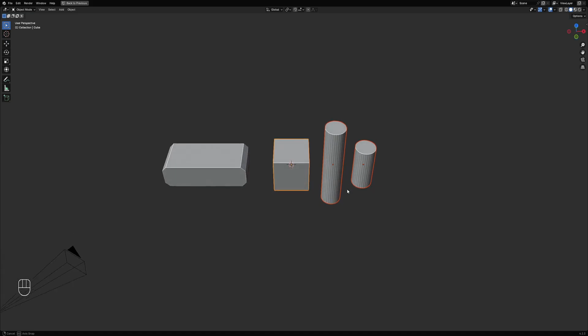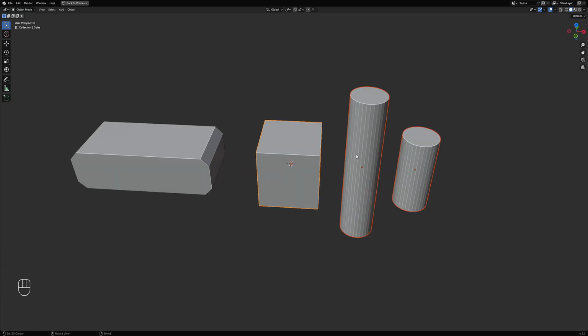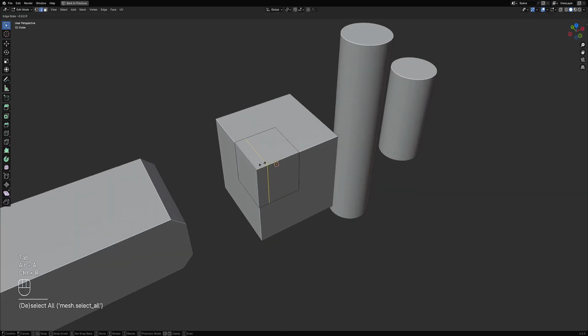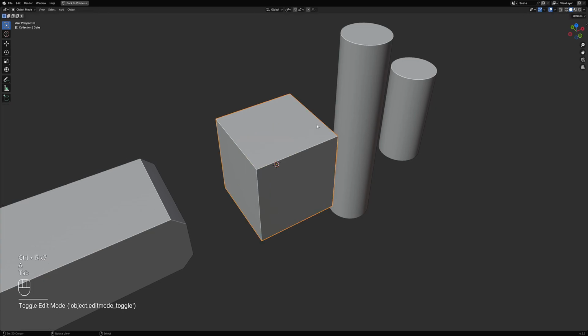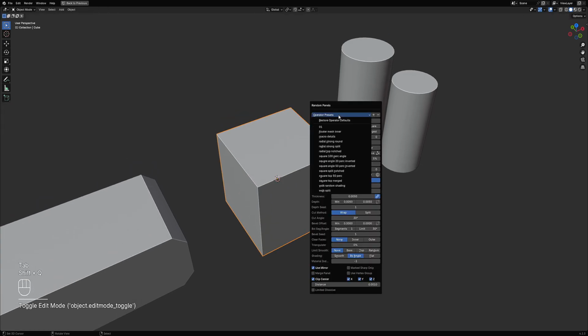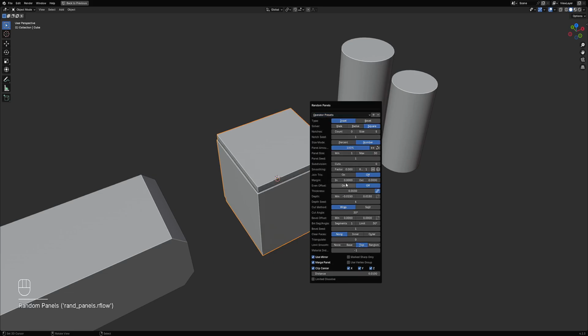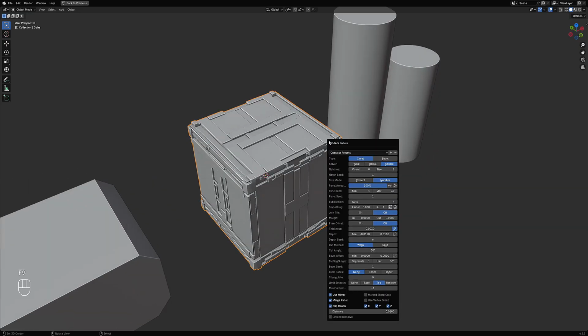And okay, let's just start with these four objects. Shade auto smooth. So this is great. We're gonna drive the entire design using randomization. And let's start with, and also use a merge. So the details will be merged to the source object. So this is a destructive process. So we're using number for the size mode instead of percent.